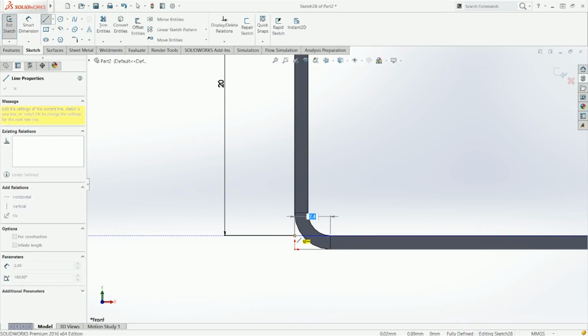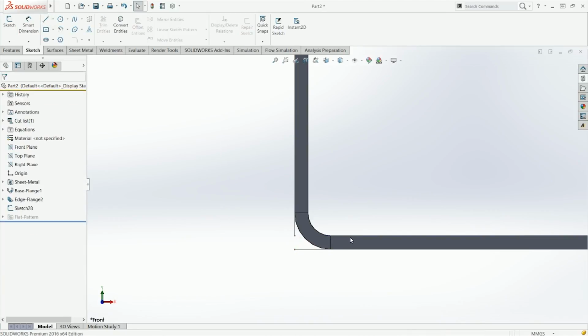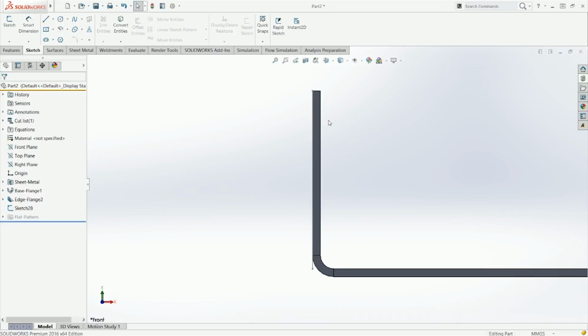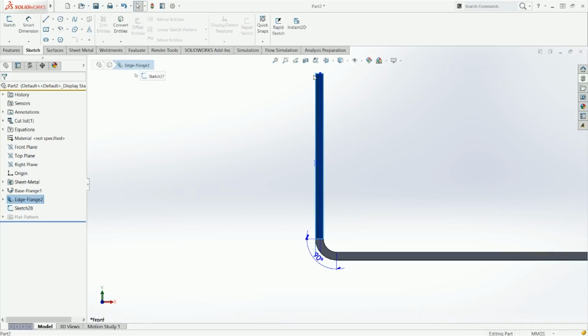Yeah. So as you see, instead of extending this line from the outer part of the sheet metal, it's going to do it from the inner part, and from there it's going to create our extended line, and we're going to get a different position for our imaginary point. So that's why the 20 mils will be defined from that imaginary point to the farthest part of the flange.